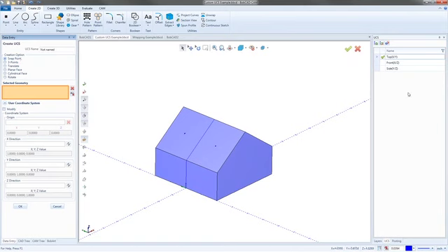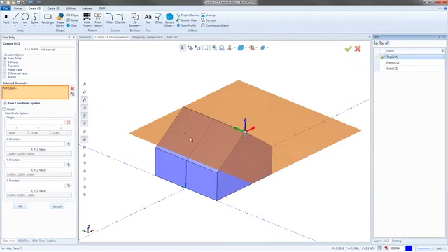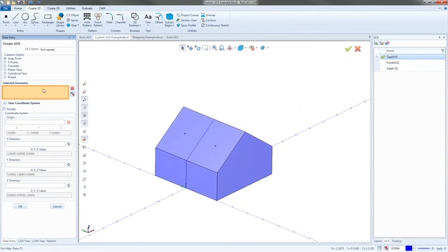So over on the left right now, I'm in a top plane, so the plane is nice and flat right here in the X and Y. If I was to go in and hover over this, yes, you do get snap points for certain functions off of your solid models as well. So what I have to do is just hover over this and then click on it. What that does is it creates a plane that's flat. So it's the same as my XYZ 0 normal top plane, but now it's at the top of my part instead of the bottom of my part, and it's off that corner instead of the bottom middle of that part. So if we want to keep that, we can hit OK. If I hit the X on there, it deletes the geometry.